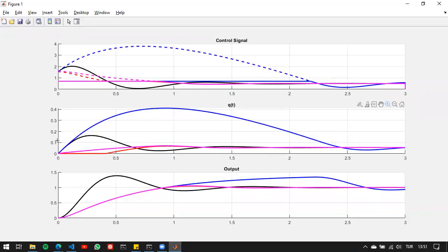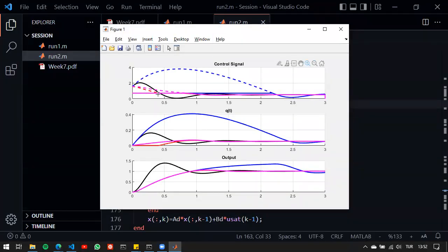So what we can see from here is that if we have an integrator in our control loop, and if we have a saturation, then it is practically dangerous to use such a control setup. And the reason behind that is the following. If we are in the saturation limit, or if we are applying the limit, then the integral is a ramp function. Therefore, it increases too much, and it increases with time, proportional to time. If we are in saturation for 10 seconds, then it will be 10 times the error value. So it's too much of a difference.